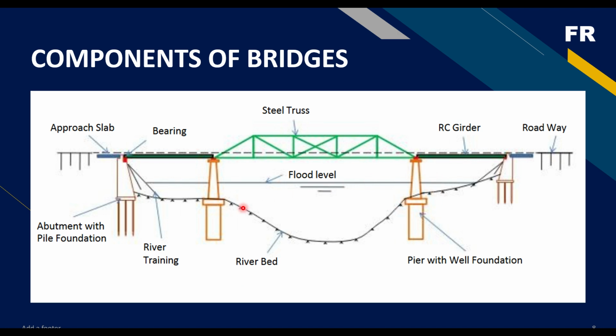These are the piers, which support the intermediate part of the bridge. And then we have the foundation. Like I've mentioned, this foundation is usually pile foundation or any form of deep foundation. And in exceptional cases, you can have shallow foundations as well, especially when the loading expected on the bridge is not as much as a standard highway bridge.